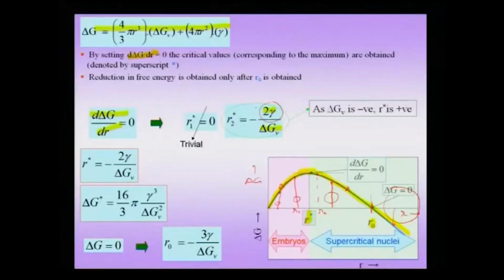Now, how does this r star actually arise? I mean, how does solidification take place? The liquid is exploring all kinds of configurations, because this is a liquid, atoms are mobile, and in some region of the liquid you would observe that atoms are coming into a precise configuration. Suppose I am talking about an aluminum crystal, which looks like an FCC aluminum crystal.